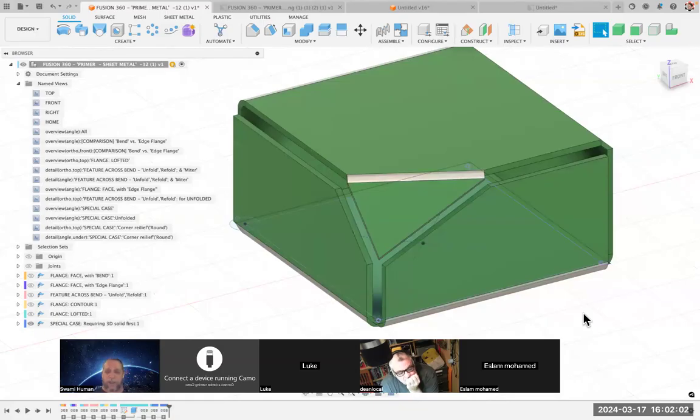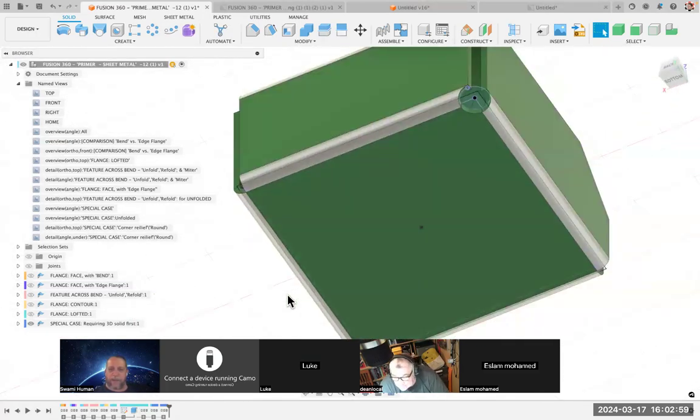The important part is no angles. So if I tried to make, like we did before, a face flange on the bottom and then make my edges coming off the four sides, then when it comes time to do this one, I'd have to go 90 degrees here, 90 degrees here. But what is this angle? It's a result of this other stuff. So I could use some math, some trigonometry, maybe some constructed geometry and dimensions and parameters, but that would be a mess. It would be very difficult to know that angle and to have any control over these distances in my design intent. So this particular geometry doesn't lend itself well to the standard sheet metal mode. You will see that there are all those cuts, and then all of the silver highlighted ones are where the bends are.